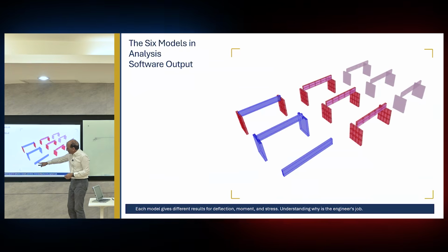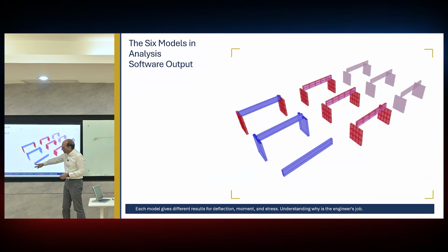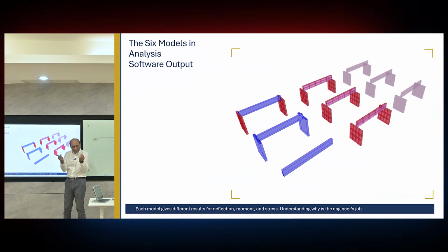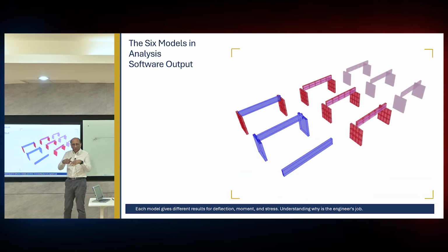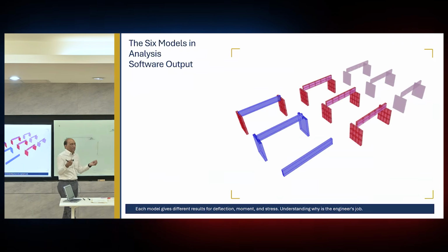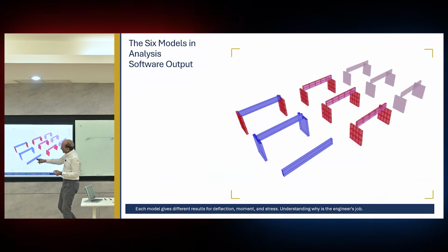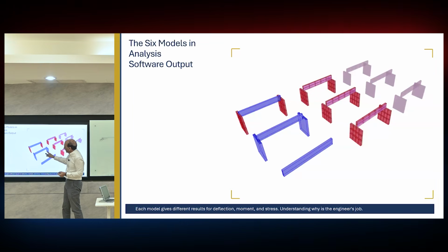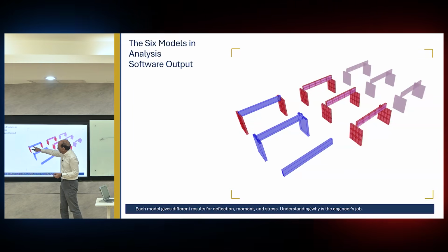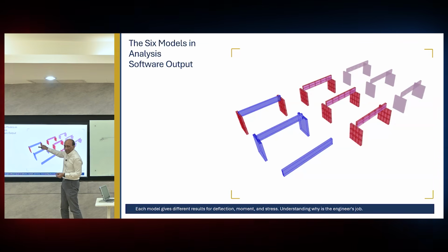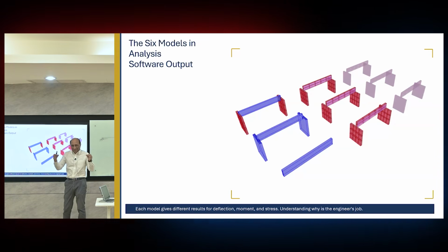So this is a simply supported centerline model. I just extrude it alone, resting on end supports, no walls. So I remove the wall and I just model the beam and put the restraints at the end. This one I modeled everything by frame. This one shell, this is framed, but it's not correct because it goes down. As you can see here, it's not at the top of the wall because I use centerline model.